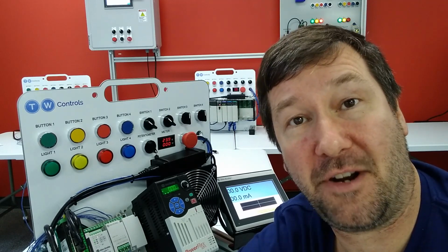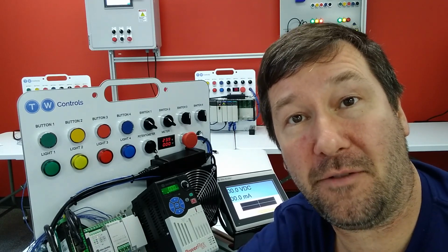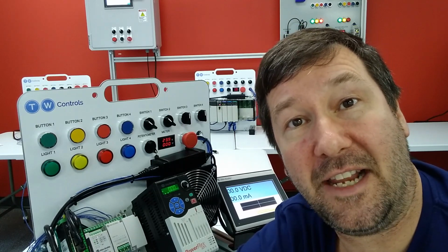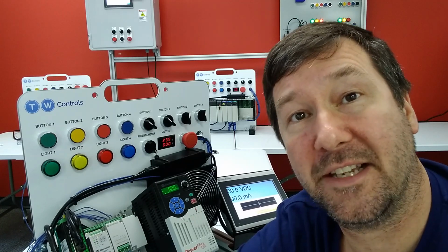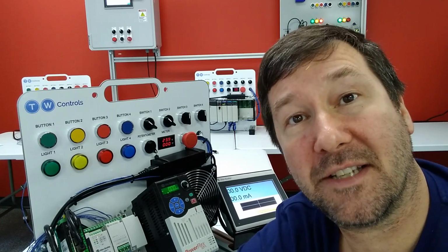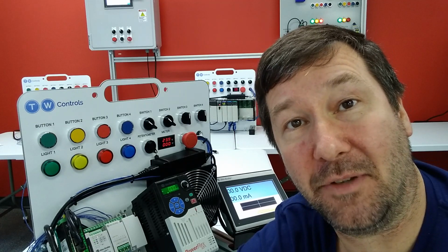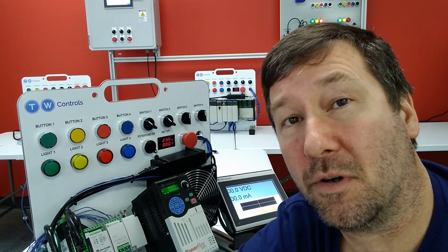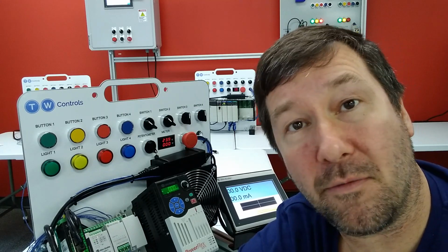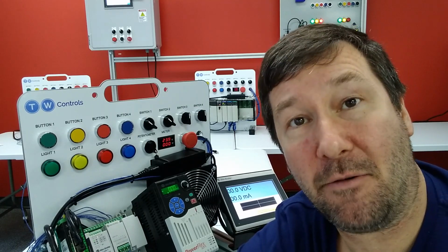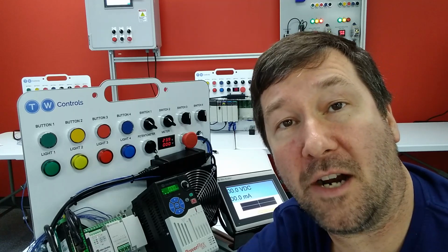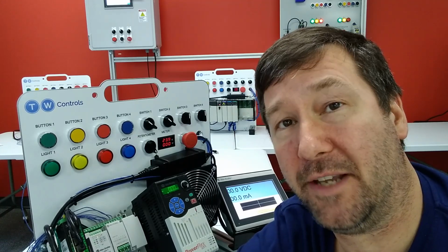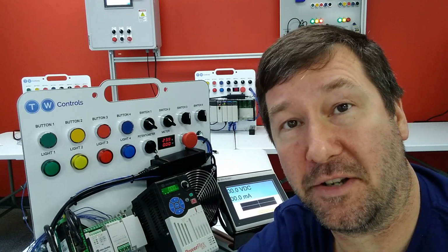It can be confusing to try to figure out how to wire a current 2-wire device compared to a current 4-wire device. The key is to understand the current 2-wire device is passively powered, whereas a 4-wire device is actively powered. Basically, that means that the 2-wire device will consume a little bit of power from the current loop to power its electronics. A 4-wire sensor isn't powered by the 4 to 20 milliamp circuit, so it only has to worry about regulating the current signal.